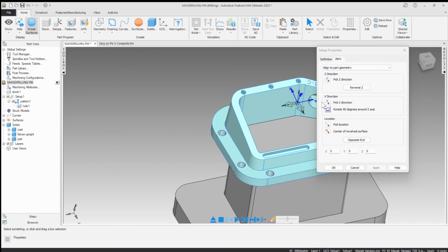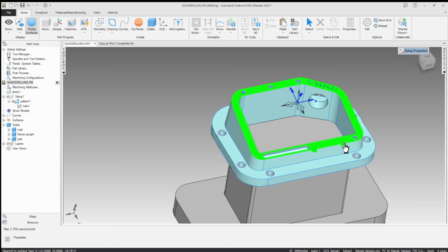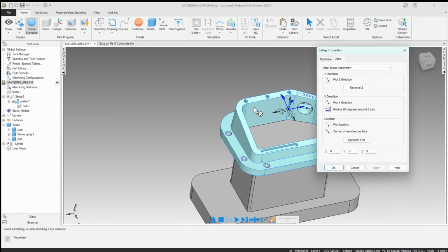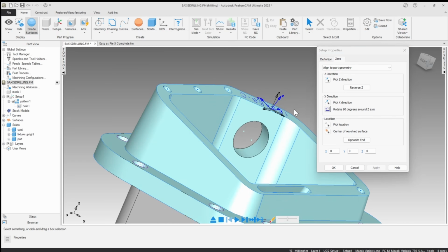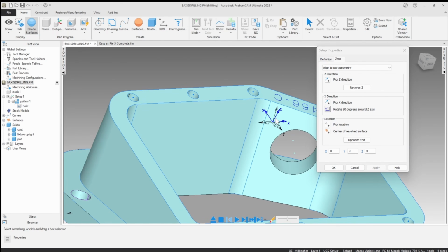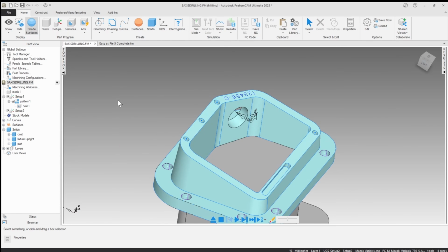We can also use an edge to kind of pick on. So right there, make it parallel to that. If you get 2 clicks, you align it up. Okay, and then where do I want it? Typically, I'll put it in the same spot as my original setup, but this doesn't actually matter where this is located because all you need to do is dial in the first one. Okay, so I'm going to leave that there for now, and I'll do some of the machining on this.